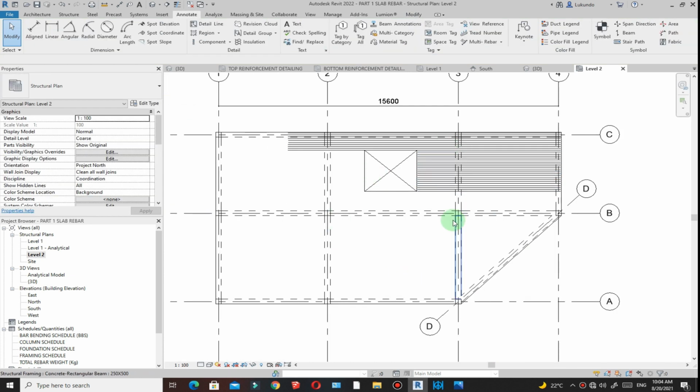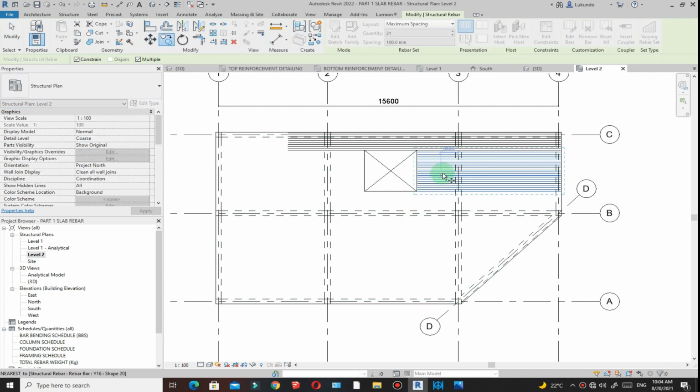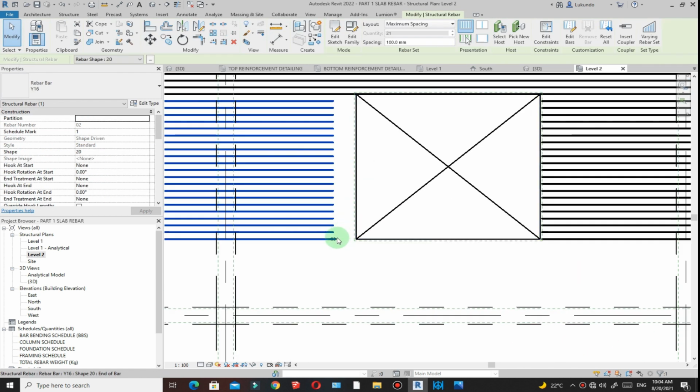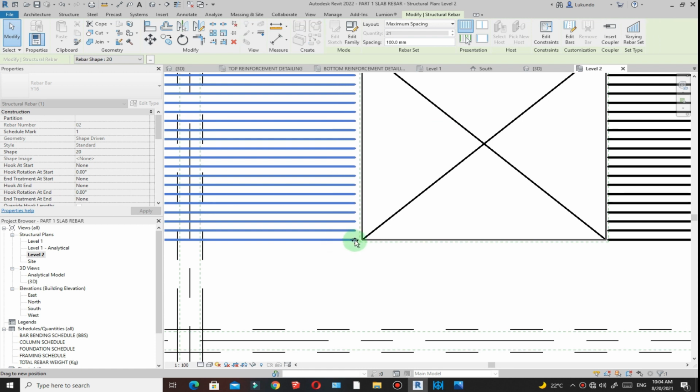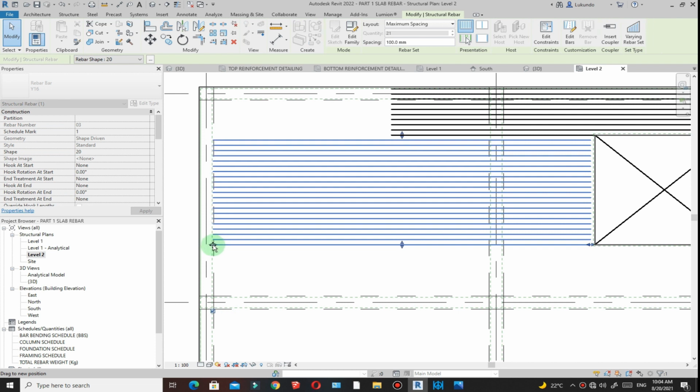Then instead of clicking there, I can still click on the rebar there, then click on copy. Then I'll just pick that point and just drag it up to somewhere here. Okay, then click on modify. Then it's just a matter of selecting on that rebar, then drag it until it snaps to the cover like that. If it's not snapping, we have the tool that you can use. Let me drag this side also. Okay, closer to the cover somewhere there.